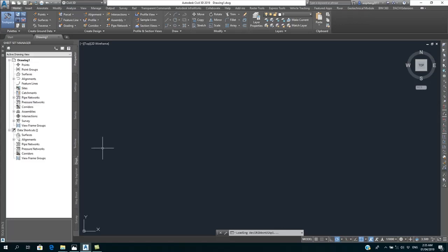Now to start, I will introduce us to the basic interface of Civil 3D 2019. This is a licensed product. For the purpose of integration with Infraworks, the first thing you need to do in the AutoCAD Civil 3D environment is to coordinate your project. This is the tool space. It has the perspective tabs and the settings tabs, which you can use to do these coordinations. And you have all the ribbons that you work with and some AutoCAD functions.